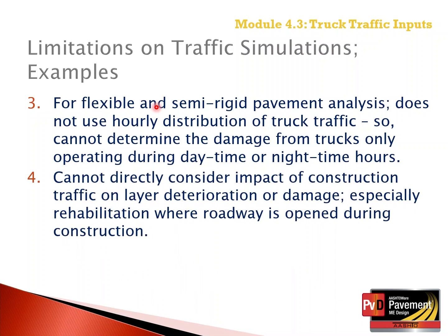Another limitation is Pavement ME cannot directly consider the impact of construction traffic on layer deterioration or damage, especially rehabilitation where the roadway is opened during construction and heavier trucks deliver materials to the roadway, as an example, the asphalt delivery trucks delivering the mix to the paving, and those trucks are riding over the in-place asphalt layer.